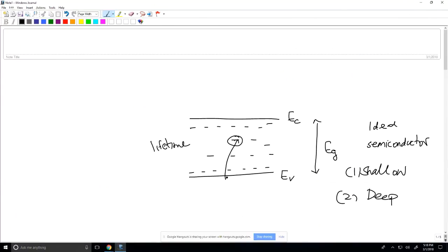What we discuss in the course are essentially ideal semiconductors. I don't discuss how we make them, but most of the semiconductor industry makes use of ideal semiconductors, so people have been making them. But for most other semiconductors which people normally process by other means, trap states also play a role in determining the carrier concentration, and that depends upon the actual semiconductor you have, and also the type of trap state and how you process them.